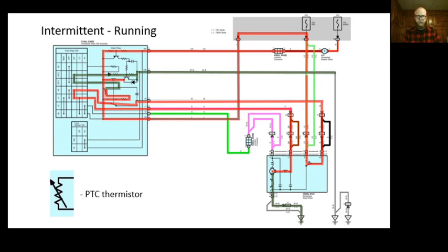I had to spend some time really tracing this through, but I think it's pretty rewarding to understand, well, I can pretty easily tell you whether or not this motor's any good. Does it have low speed? Does it have high speed? Does it park? If it does all those, it's not the motor. So I can move away from that. Like we're saying, the customer comes in with an intermittent wiper inoperative issue. Then I can look at the switch and be like, golly, there's a whole lot of stuff going on inside of that switch. Well, if the wiper motor's good, is there a circuit that's specific just to that switch? Let's see. That makes it so we have intermittent. This wire's for my low speed.